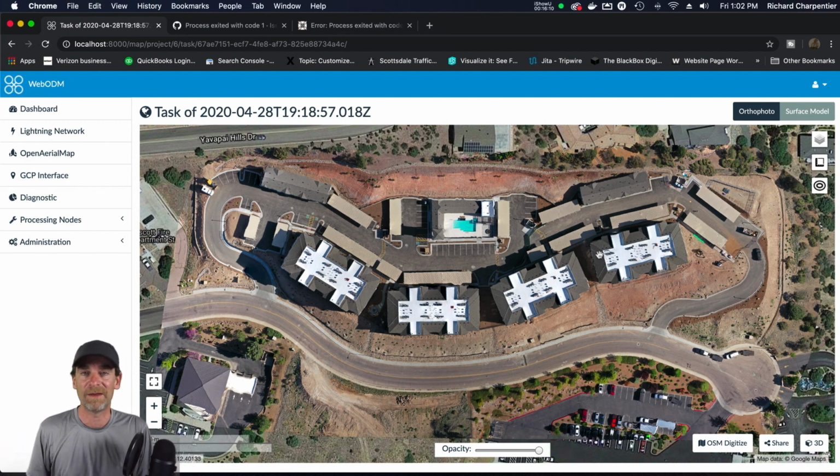So the data set that I had from the construction site that I've been using in Metashape worked out really well and worked with WebODM. Neat, really neat. This lined up pretty nice, but not perfect. If you look around this, if you hit the pause button, you'll notice over here, this driveway is not really lining up perfectly with the road. It's off by a couple feet. Same things on the other edges.